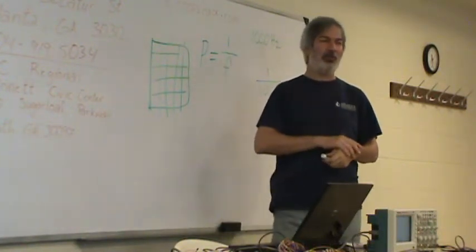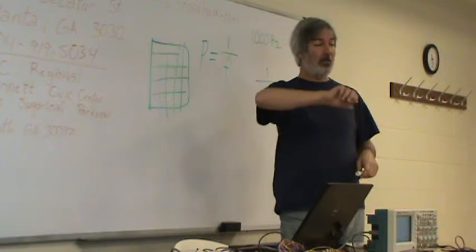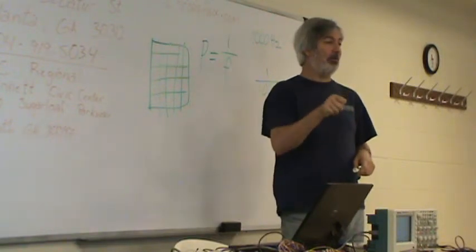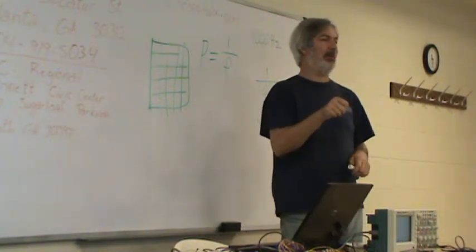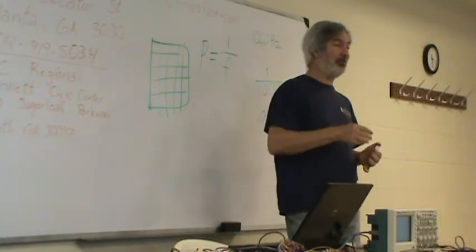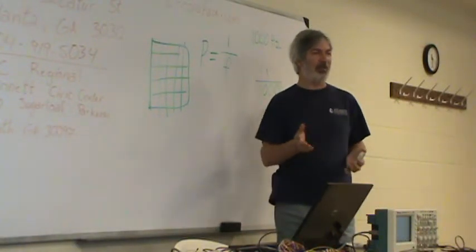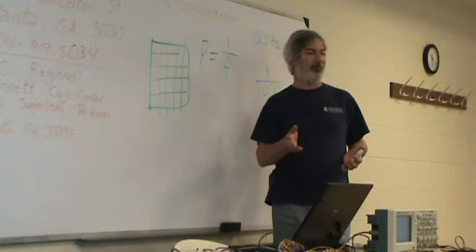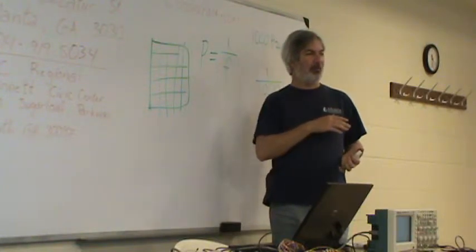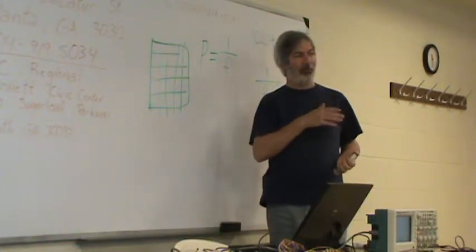You start with a very fast sweep rate, and you just start turning it down until your signal shows up. And like Dale says, you won't show the aliasing, because aliasing is where you've got a slow sweep and a fast signal.